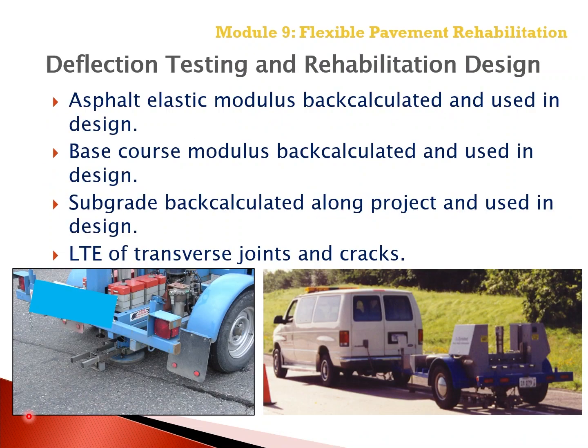Deflection testing can also be used specifically to provide inputs for the rehabilitation design. As an example, the asphalt elastic modulus can be back calculated and used in the rehabilitation design. It's a direct input to the Pavement ME software. In addition, the base course modulus or a stabilized base layer modulus can be back calculated and also used in the rehabilitation design.